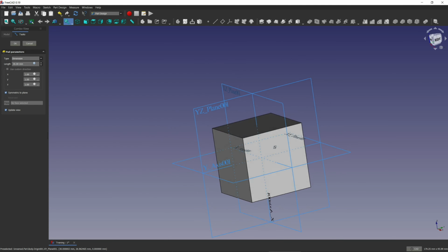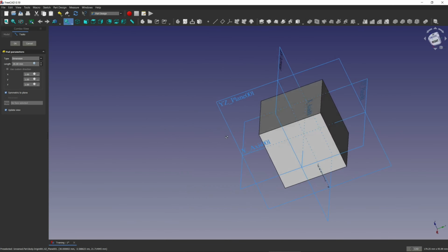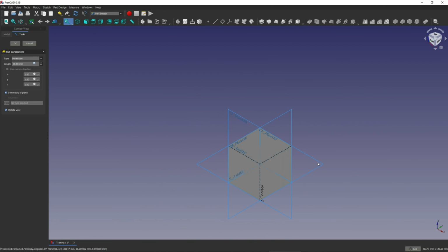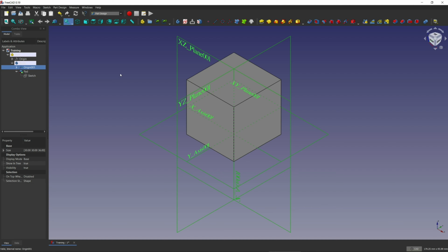Yeah, so like how we created the cube in the first place, we had a sketch and then turned that sketch into 3 dimensions. So we need to use the same methodology here and draw a 2D sketch of the hole that we want to create, and then use that in a three-dimensional sense to remove the material. Which is known as a pocket.